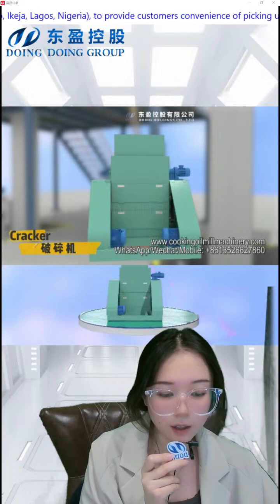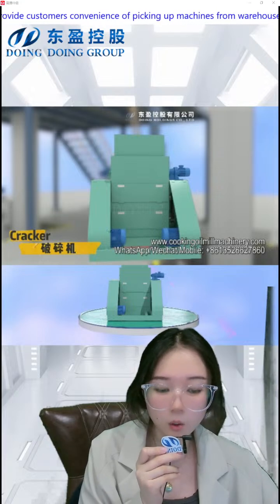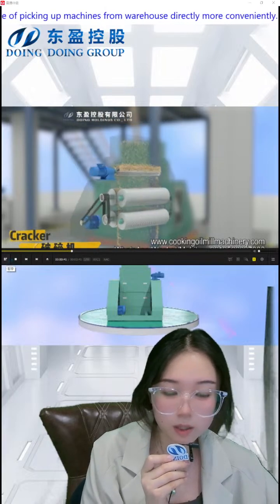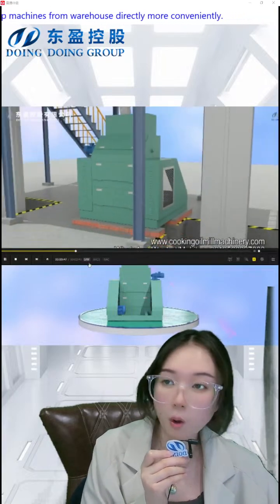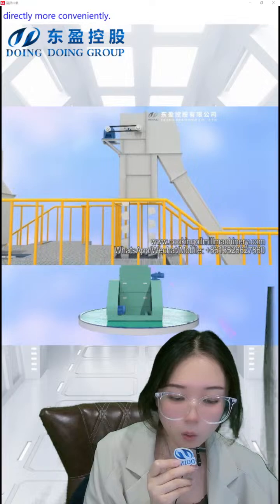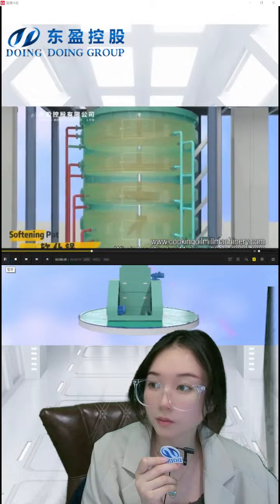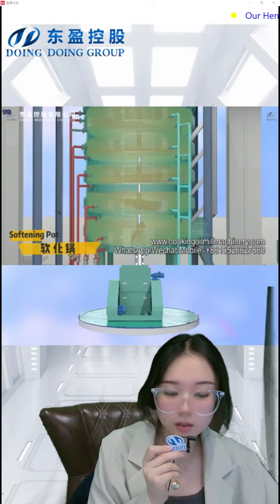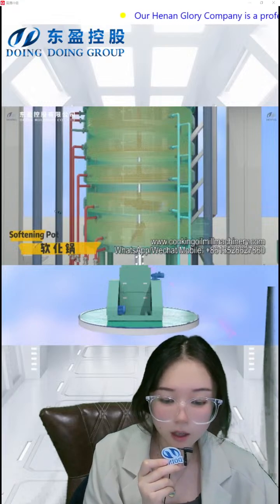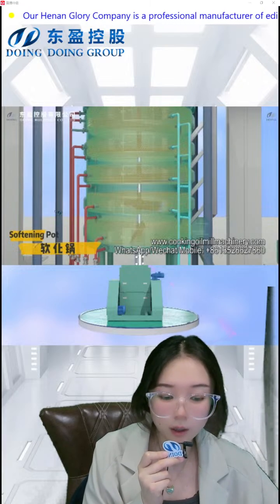Due to the relatively hard texture of soybeans and peanuts, after cracking, the raw materials will be transported to the softening part through the bucket elevator, where direct steam is introduced to adjust the moisture, and the temperature is maintained at around 90 degrees.